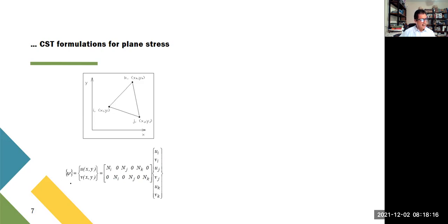In general, v in the element is equal to vi times ni of xy plus vj nj of xy plus vk times nk of xy, in the same way as we interpolated u.